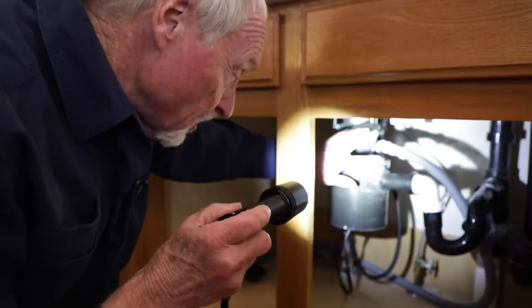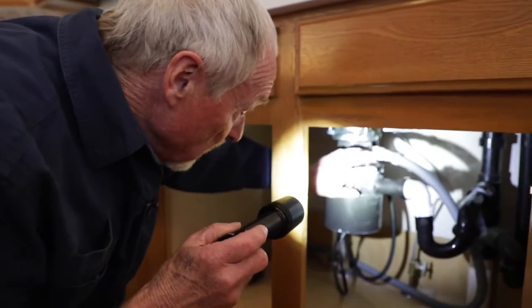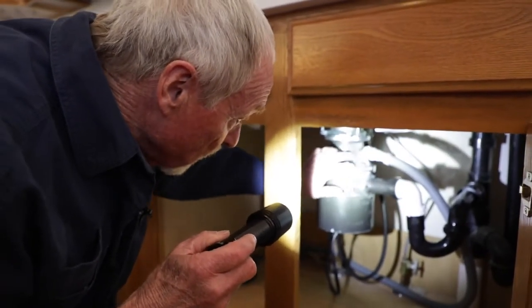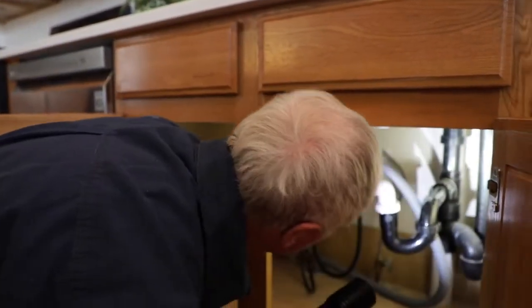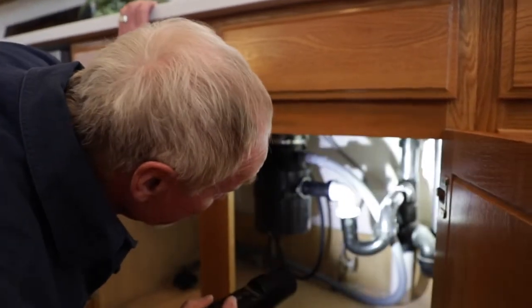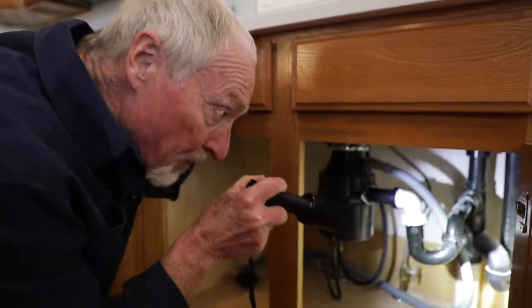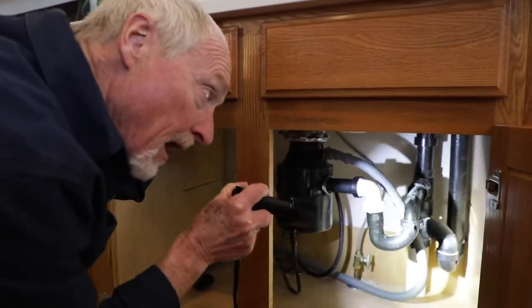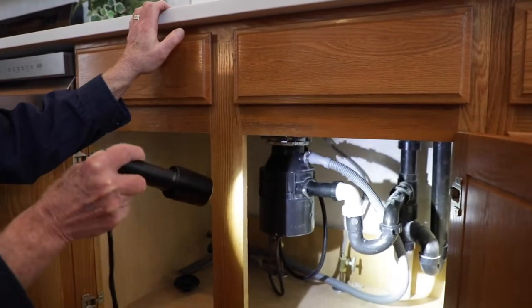In some areas, some jurisdictions, municipalities flat out say you can't hook the dishwasher discharge into the disposal if you have the alternative drain set up there. So in this case, it's certainly the best practice and smart. For one thing, that P-trap that we see there can dry out, and we can get sewer gases leaking into this kitchen.